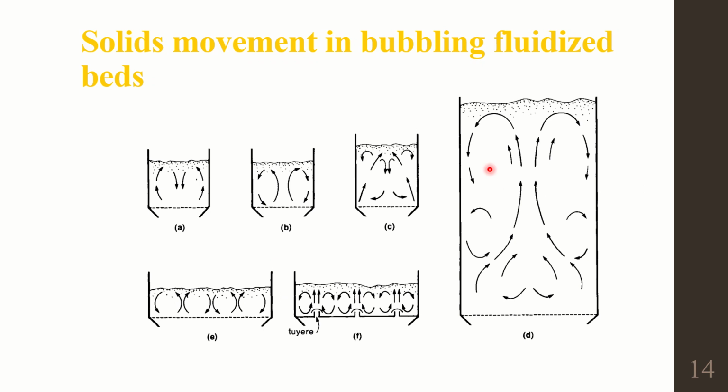So this is the general fluidized bed pattern with the very high depth compared to this dimension. Here it is similar to that, where the particles are going from here to there. Like in a general fluidized bed, particles would be going from the center to the top. From the center they would be traveling upwards, and near the walls they would be falling downwards, and some recirculation would be happening elsewhere. So depending on the bubble movements, the solid pattern is highly influenced.